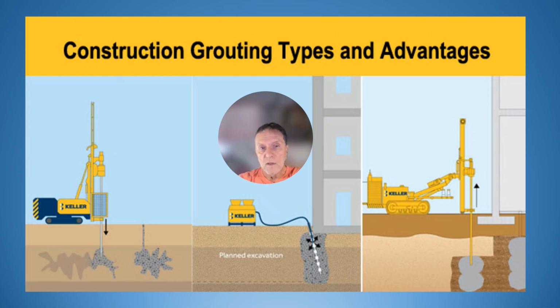Construction grouting. A grout is a type of cement that is often used to fill in voids in a natural soil or bedrock condition. For example, in Florida, there's sinkholes and other types of voids, caverns even, because of the limestone and the dissolution of the limestone by groundwater. So if you're building on top of this type of terrain, you might want to fill those cavities, and you do that by introducing grout, which is a cement mix to fill the voids and give stability to the foundation conditions.